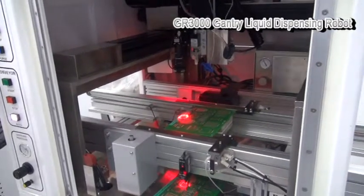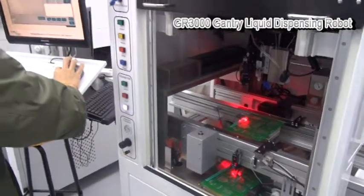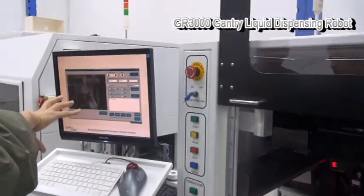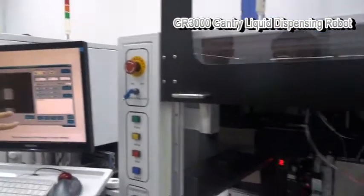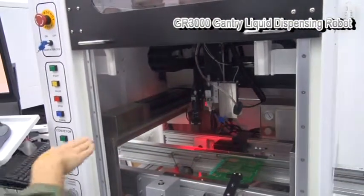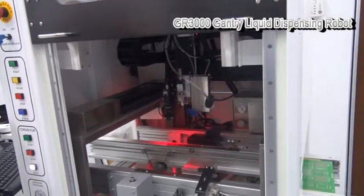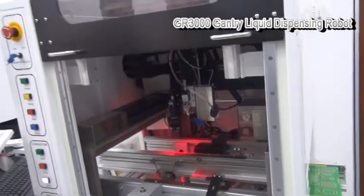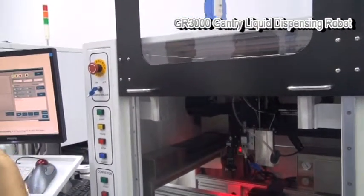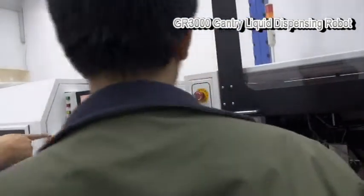And then I will show you the camera mode one. Yeah, this one, the fiducial process. I just need the dot, because whenever the board comes in, the system will compensate faster. Whether the board has an offset or orientation, the system will compensate and then move it back to the correct position. So can you show one more time?